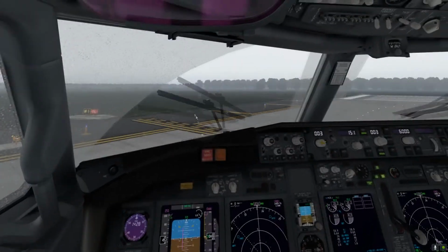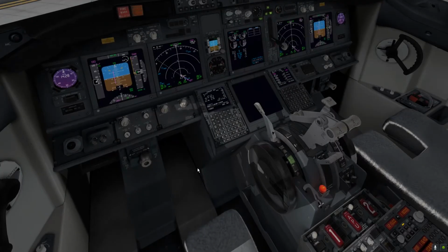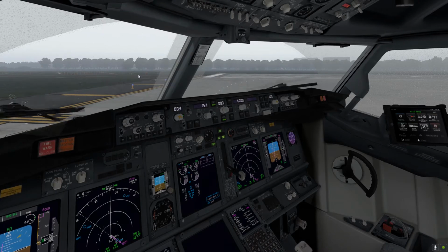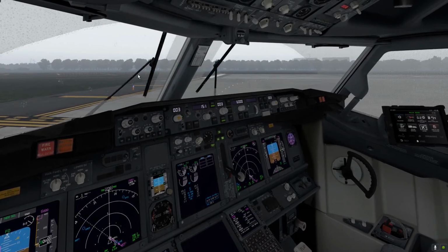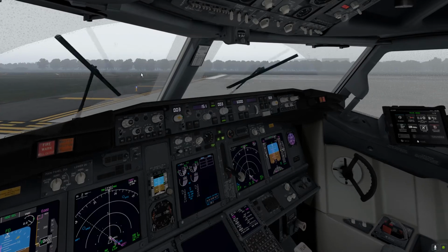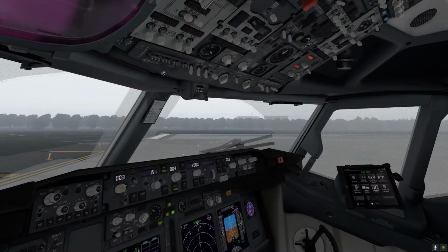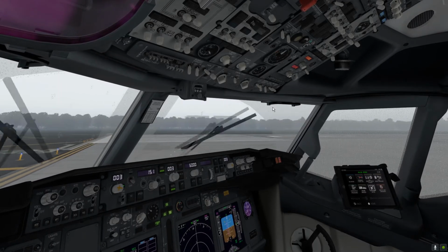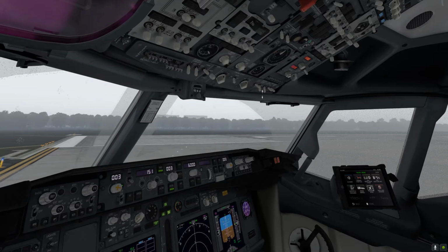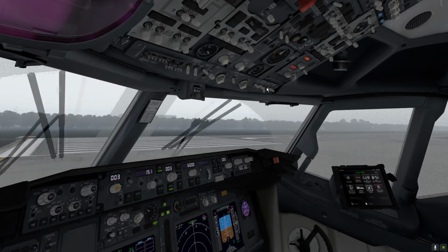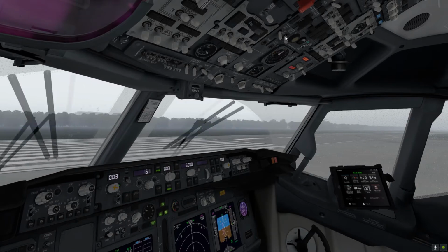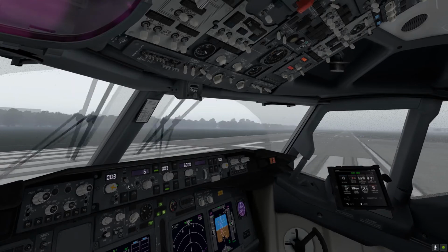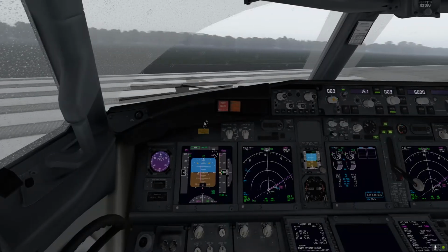So cabin is ready, and we have been cleared by the ATC for lining up and takeoff runway 01 left. So let's go with it, let's go for it. Captain takes care of the exterior lights. First officer switches the strobe light on. Cabin is being advised like that. Cleared for takeoff.